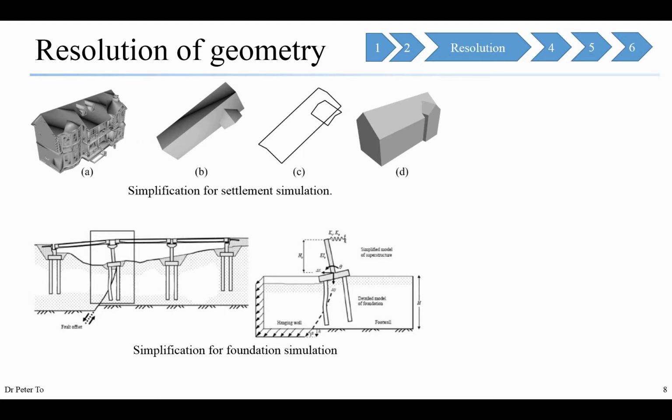In terms of the square, you can have quadrilateral or hexahedral elements. In terms of the nodes, you may have linear elements, where we have nodes only at the vertices of the elements. Or you can have quadratic elements, where you have mid-side nodes. Please remember that mid-side nodes are computationally expensive, but they can represent curved geometry with fewer elements.